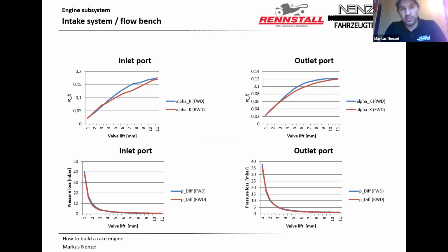It's quite interesting, because you have waves in the intake system. The air does not just go from left to right and then everything is fine. You have some backward movement. Because of this, you check the inlet and the outlet port, and you check forward and backward flow, because sometimes the air can go back with the resonance waves and so on. You have a look at both directions.